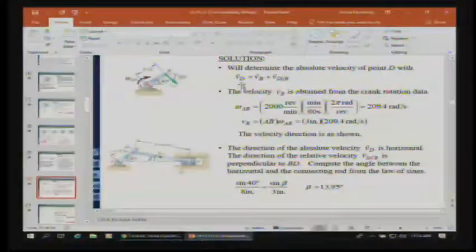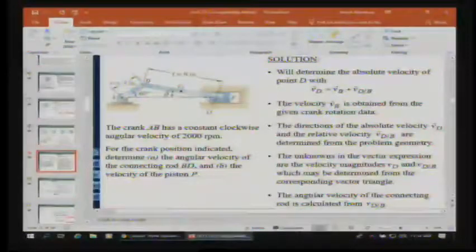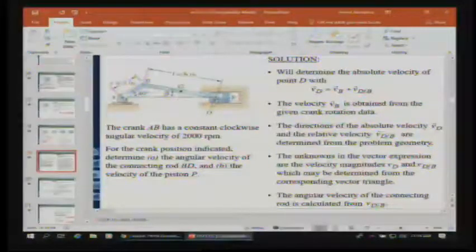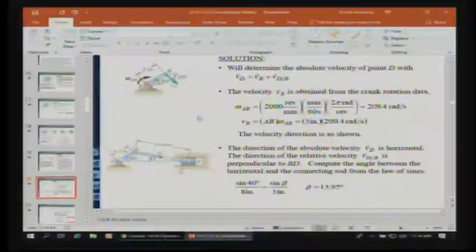But working through the problem that way, when we start looking for the velocity of point D, we can think about it as being some sort of a translational velocity with some sort of a rotational velocity. And in this case, we can start from right here, which is where those two arms connect. And we can say that it's the velocity of B, which is not going to be purely x or y. It's going to have some sort of a component at that point, plus the velocity of D with respect to B. So we can find the omega and the velocity of B.